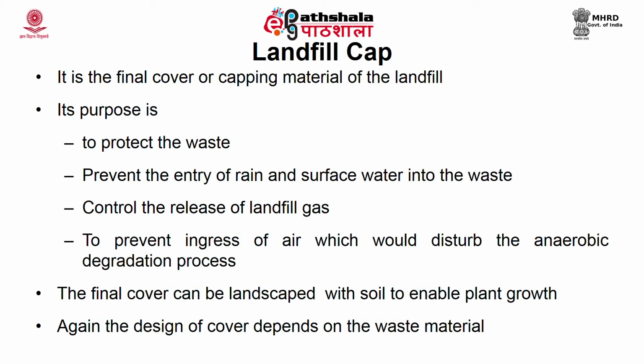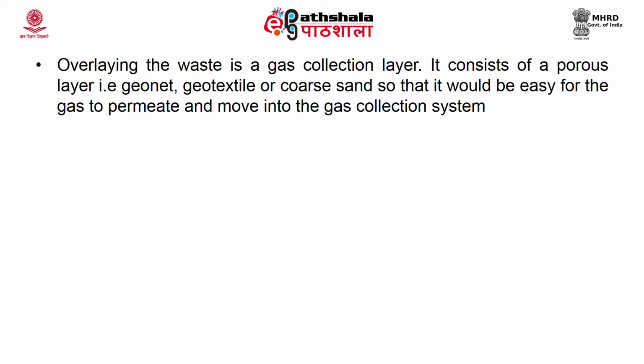Now, the structure of the cover material, the landfill cover, will be like this: the waste will be there. On top of the waste you will have a gas collection layer, and the gas collection layer will be a porous layer made up of geonet, geotextile or coarse sand, so that it is easy for the gas to permeate through this layer and enter into the collection system.